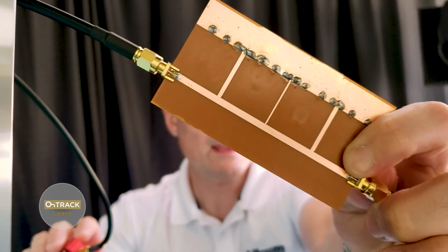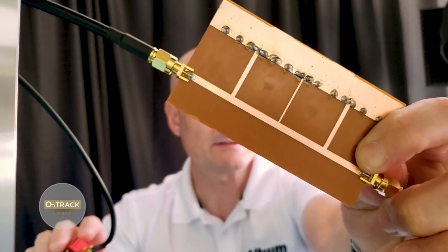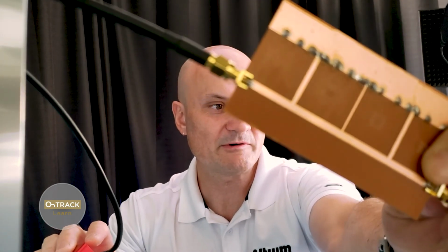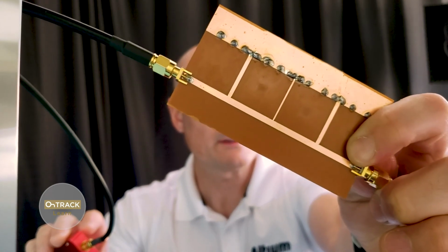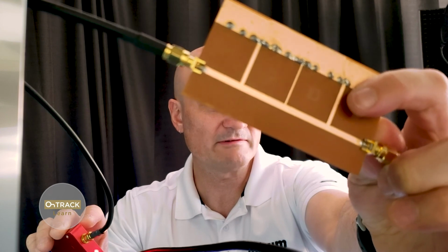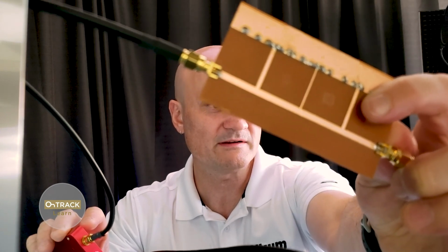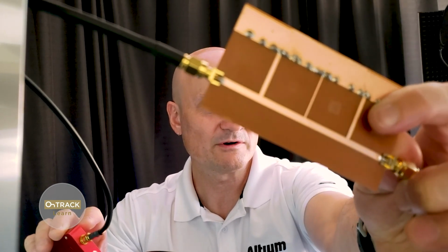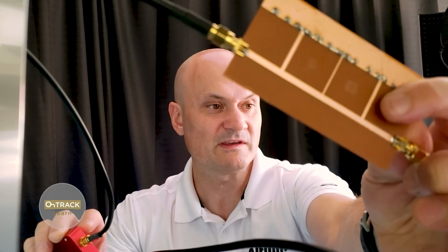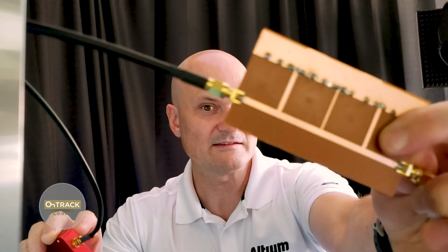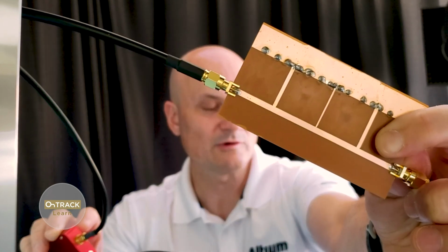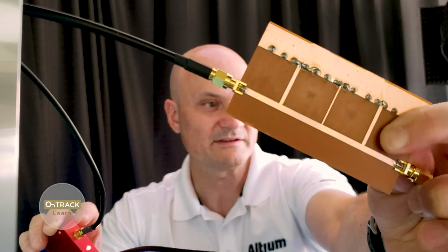You can see this one has just series transmission line and quarter wavelength segments separating those with some shunt inductances, but of course they're a quarter wavelength long. So what does a short circuit appear as? It appears as an open at the resonant frequency or the center frequency of this, but this is a band pass filter. Obviously at DC or low frequencies it's a dead short to ground.